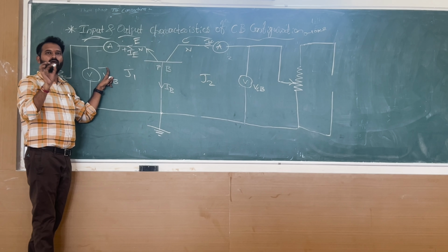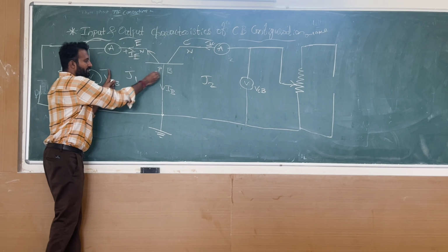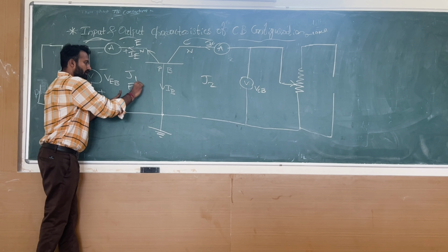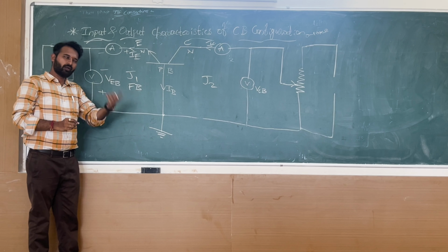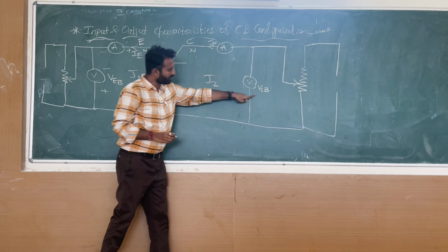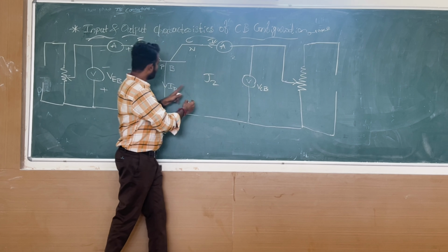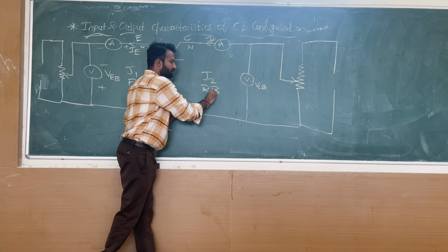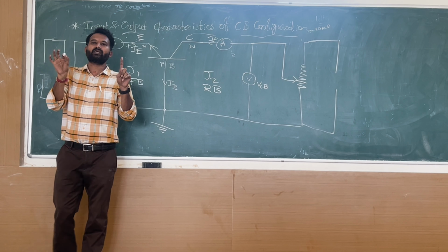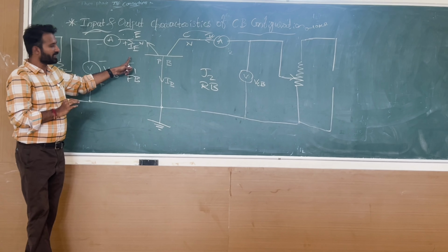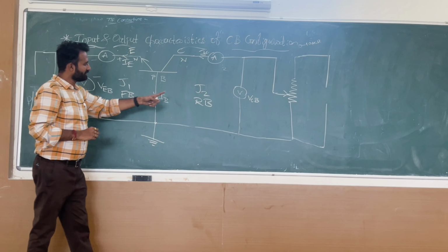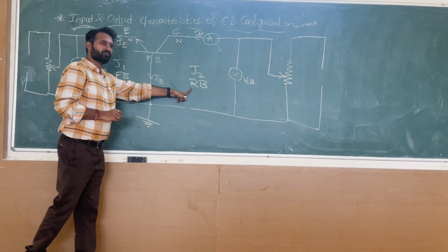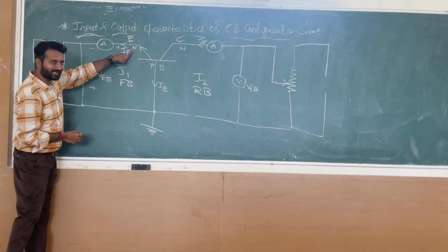Someone is saying those are the two important statements. Always keep in mind, the emitter base junction is always forward bias. Always collector, that's why I wrote it as VCB. This is what? Collector base. This junction is always reverse bias. Always, I'm giving a statement: always EB is forward bias, always CB is reverse.